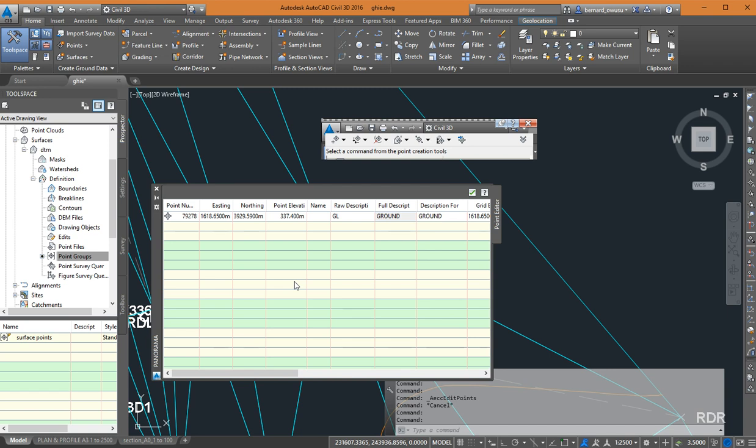So I've been able to do it. Okay, so what we are going to do is the elevation. Edit point. Have you been able to do it? Do you have this? We are going to just assume, it's an assumption, that instead of 337.4 or whatever elevation you have, the decimal comes after the second number, so it's 33.74. So just click on point elevation and edit it to 33.74.